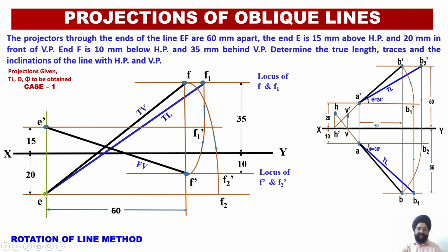I'll keep my needle over here, at E. Now as I told you earlier, there are intermediate barriers 1, 2, 3, and I am least bothered about these three. Why? I know a simple fundamental: my plan projection line is inclined, and I want to make this inclined plan projection line parallel to the vertical plane. It will become parallel when I rotate this point F up to the locus line of end E. This is the long locus line of end E which I have drawn with 2H.